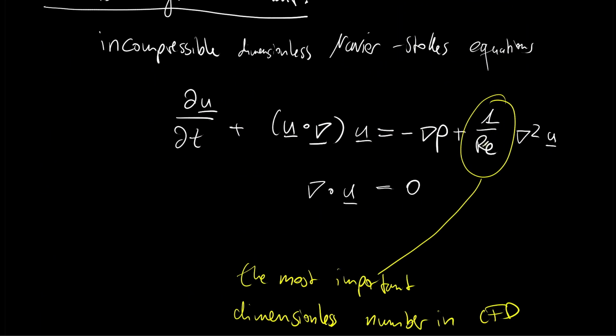So if the Reynolds number is getting super large, then we are dividing 1 by something that is super large, which is approximating 0. Then the effect of the Laplace operator, which in essence is a diffusion, will be going to 0, whereas the effect of the convection, which is this quantity here, will become dominant. You can for this ignore the inertia term and the pressure gradient.